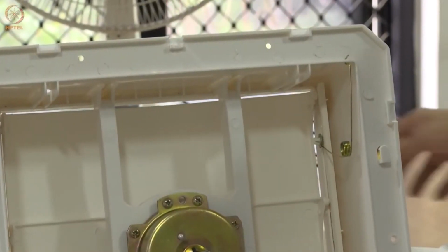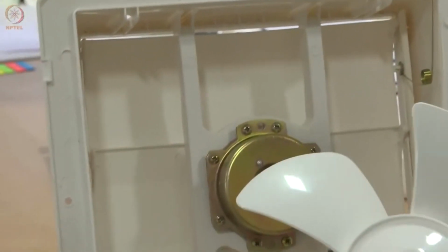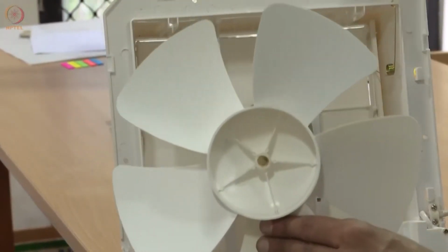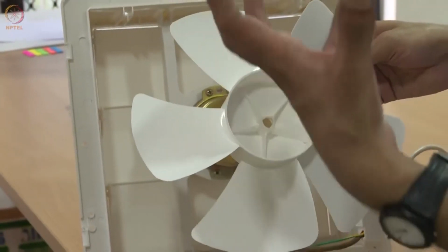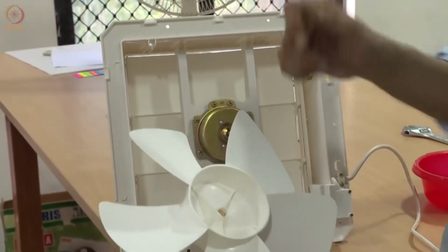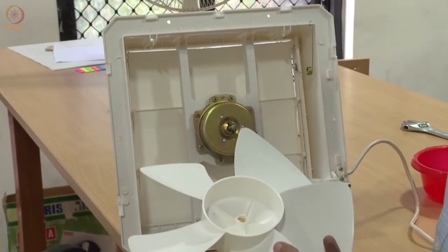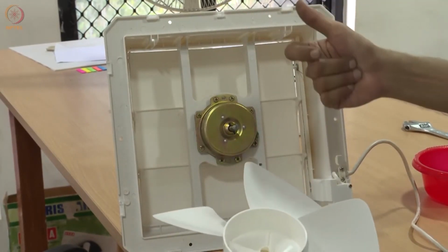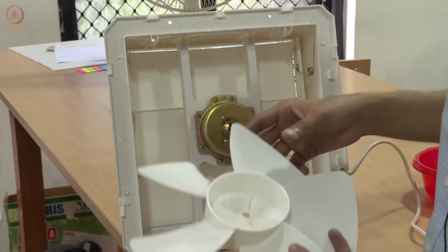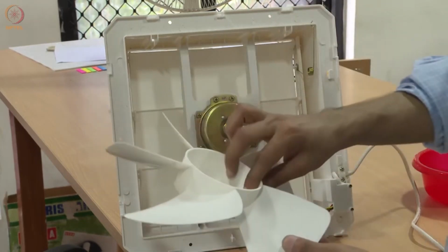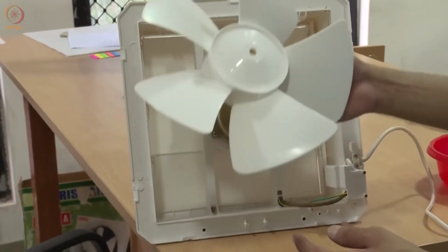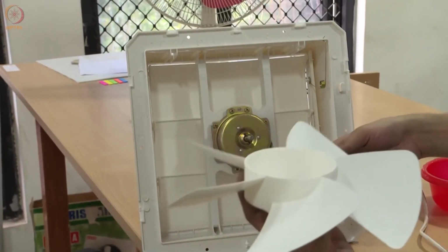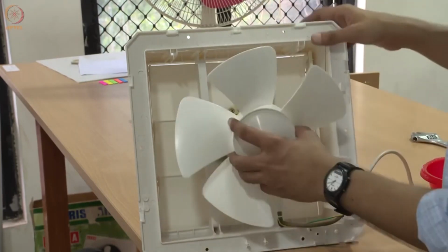So let us proceed to put the fan together. You can see the entire fan is a single piece design. The previous fan we saw was constructed out of 5 pieces held in place by rivets. It is expensive because it is made of sheet metal, and you have to make sure it is statically and dynamically balanced. In this case, because it is injection molded, the tolerances can be controlled much more finely, so it will come out properly balanced if the process parameters are properly controlled.